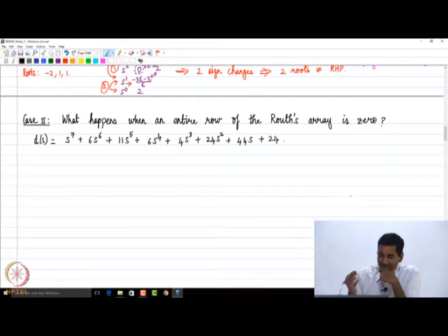Yes. So, suppose you have a 7th order system whose transfer function denominator polynomial is this, then how do you find out whether it is stable or not? Now we see the usefulness of the Routh criteria for control system design. This course is not about general math; how do we apply those mathematics to control design? That is what we are interested in. So, let us construct the Routh array and see what happens.